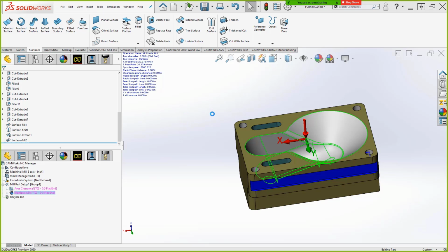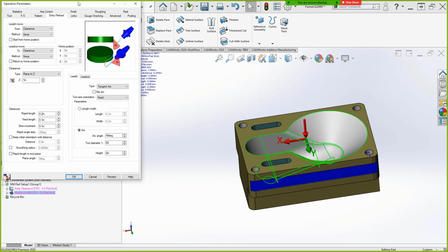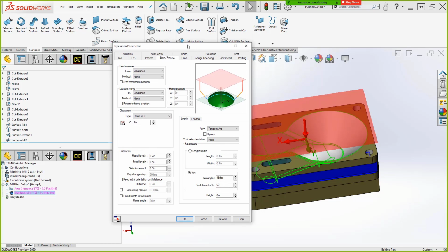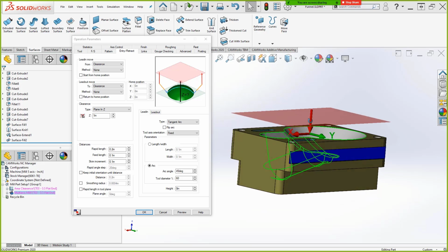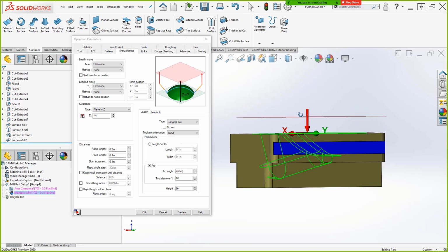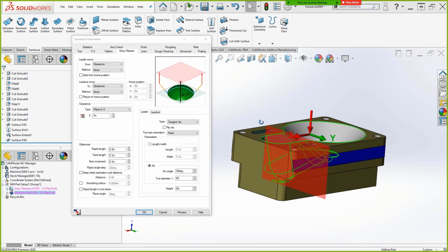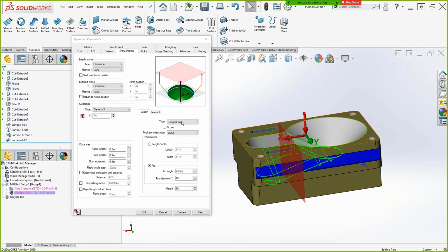as one of the more robust toolpaths, one of the larger toolpaths, more complicated options, it does take a while. That's why it's good to have these options, because if you make a mistake, you could be waiting a while for code to generate that you found out wasn't good. So this clearance plane preview is now a nice option. Kind of shows us where that clearance plane is, where it would be present based on the origin.